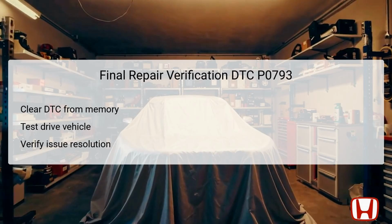Observing the vehicle's performance during this drive gives insight as to whether the repairs have rectified the issue. Listening for abnormal noises and checking for warning light activation are critical during this step. Ultimately, confirming that the initial symptoms and error code do not reappear is essential before concluding the repair process.